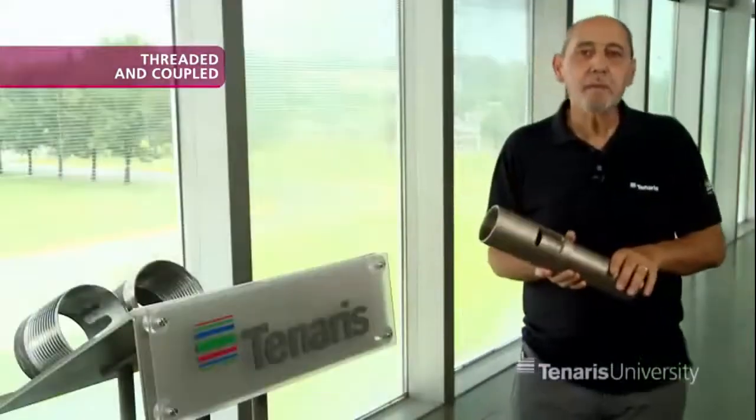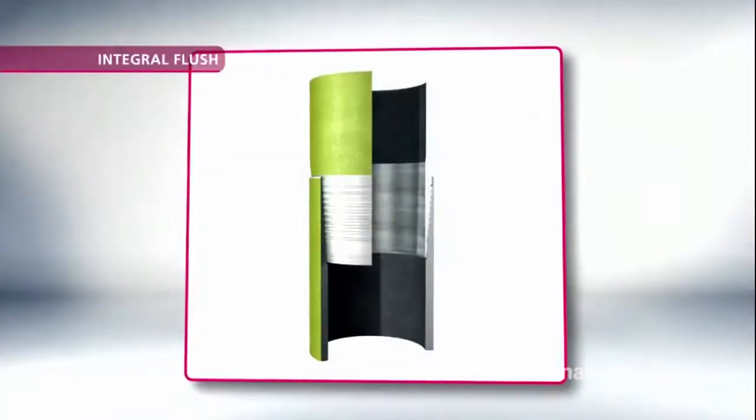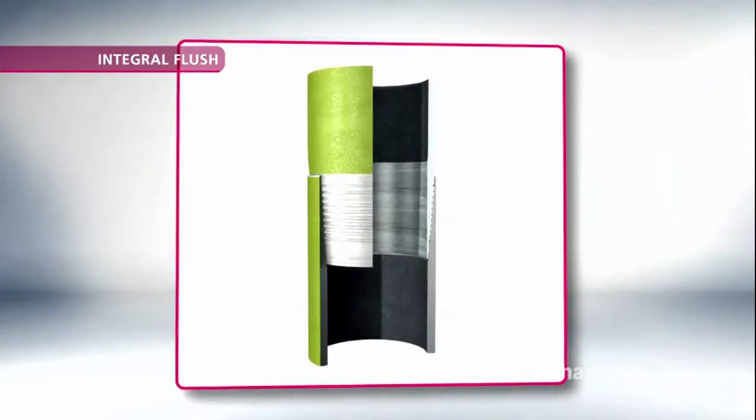Apart from the threaded and coupled connection, we have the integral connections that, as explained before, join two pipes without a third element or coupling. Depending on the application, integral connections can be classified as integral flush connections, where the OD of the connection is the same as the OD of the pipe. So the entire string has a continuous and equal outside diameter. These connections are used in wells in which clearance between pipe and pipe or pipe and hole is critical.